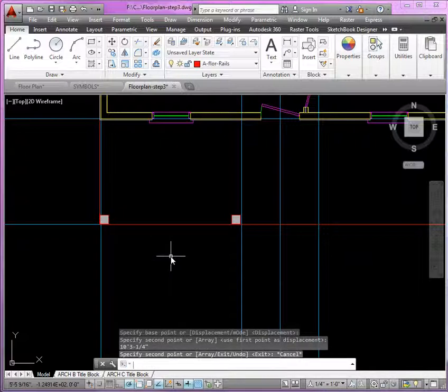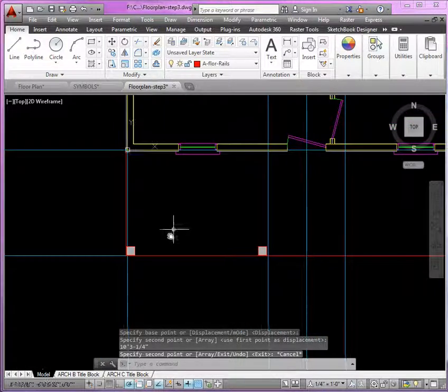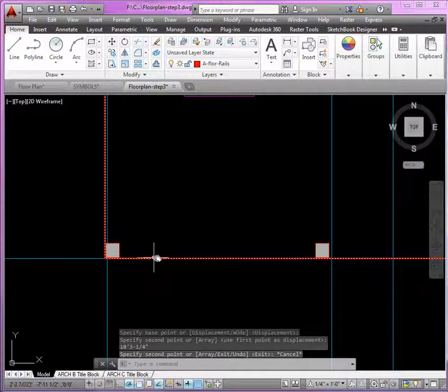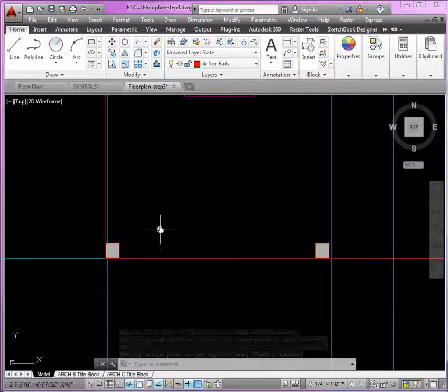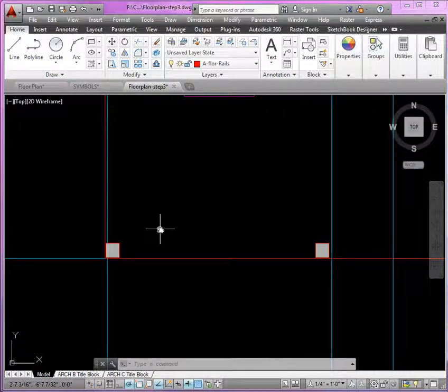All right, we'll continue here by showing the railing, and I believe we have a 4.5 inch top railing there. So if we simply offset this line here 4.5 inches, then we could trim and we could restore the layer.